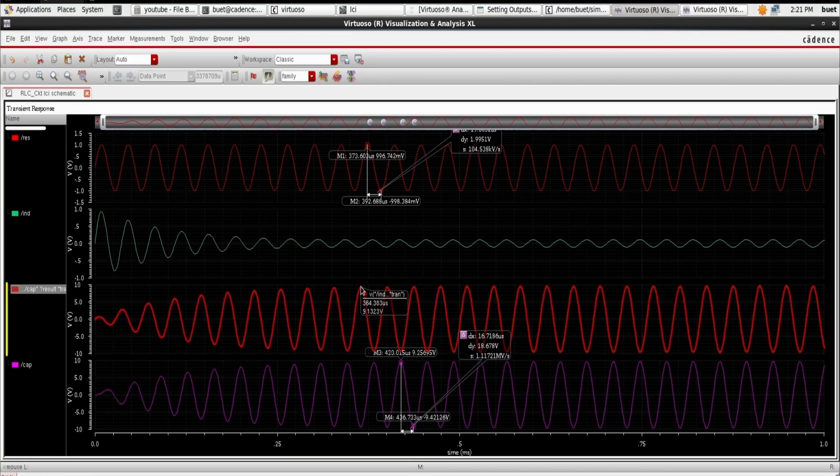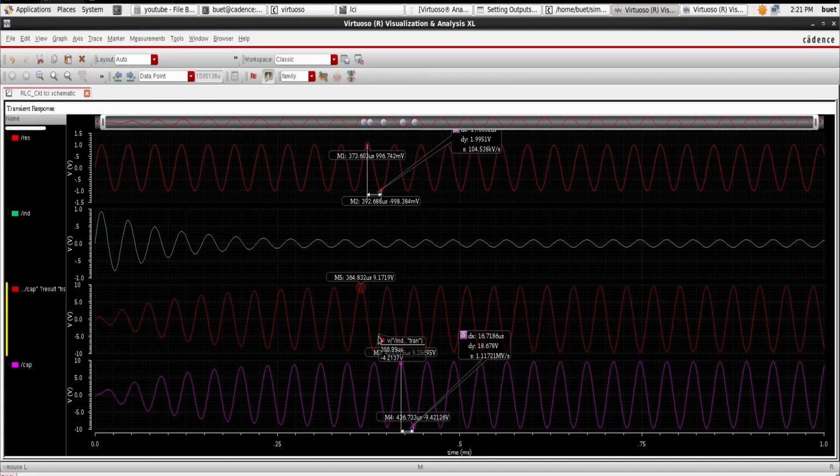So this is our new inductor voltage. Let's give M here to mark the graph and D down here to find the difference. Here too we can see the voltage is around 20 volts for our input of 2 volts. So from this we achieved our targeted value.